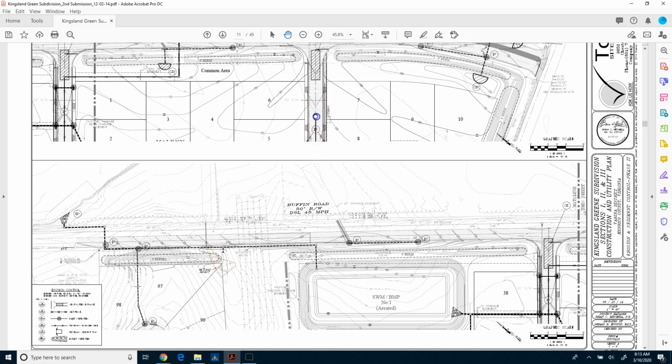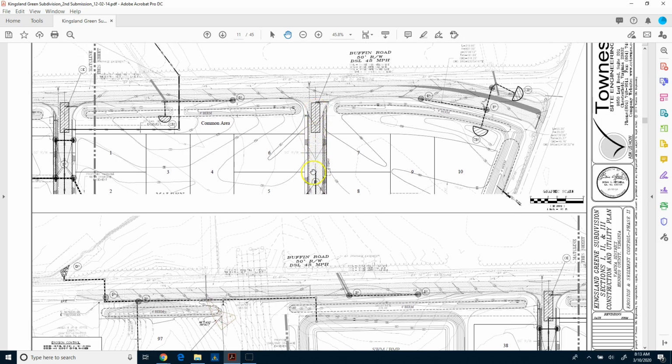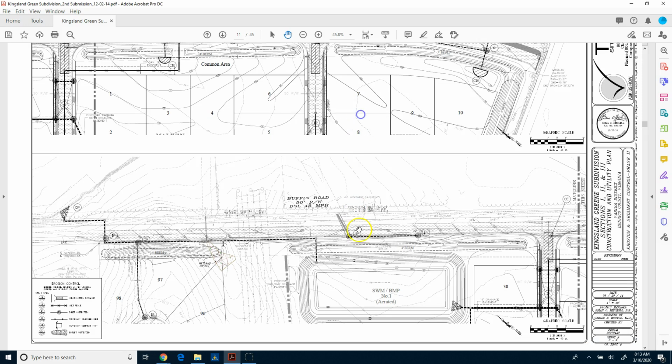So during the next phase of the construction, where they're building the roads, you can see the construction entrance is going to be in these locations. You can see the CE. They're going to be putting in a berm. So this is some of the grading. So down here we've got the basin as well. So again, this is the measures that would be applied once they get to this phase of the construction, which is phase 2, and they're going to apply that information.